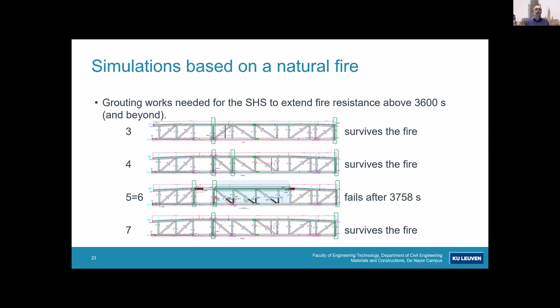And then we have the truss beams 5 and 6, which are going outside. That's the reason why there is a light blue shaded area here. There's an area which is outside. Therefore, we injected some blocks with pure foam, and then we injected also completely the grout here. Also for the upper part, which is outside, you see that we have 1, 2, and 3 vertical ones, and then for the 7 it's like number 3, and they survive the fire.